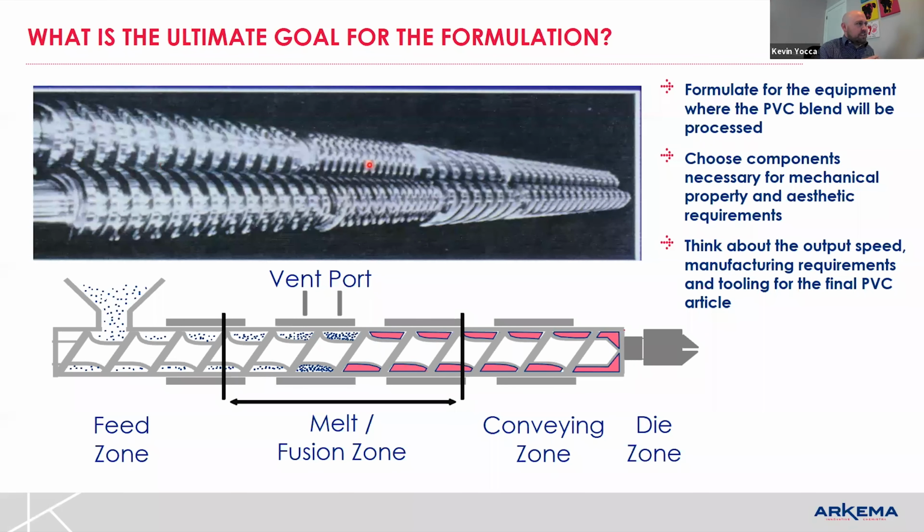So we get something loosely aggregated, associated. I've always been taught it's like cottage cheese, but really when you look in the port, it depends on what you're making and how aggressive you are. You may see something that's like a rubber band stretched around the screws, or you might see something that looks like dough kneading that's less developed in terms of the melt. It all depends on what you're trying to make and the speed of the extrusion. So it's totally up to that application.